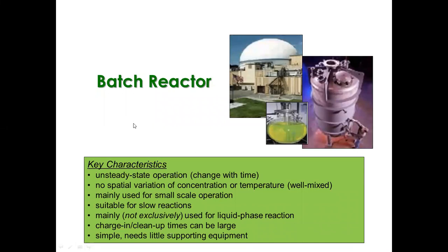It's an unsteady state operation, just like the semi-batch, or this one is just the batch reactor. It's unsteady state because there is a change in the composition at any time inside your reactor. It's also unsteady state because anytime we can change the mode of adding the reactants inside the reactor, the same thing with the removal.